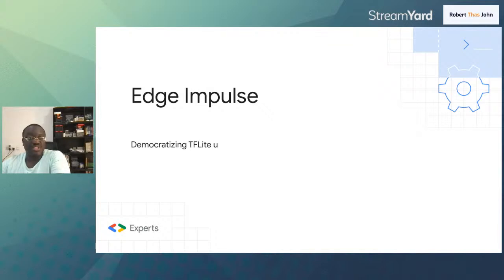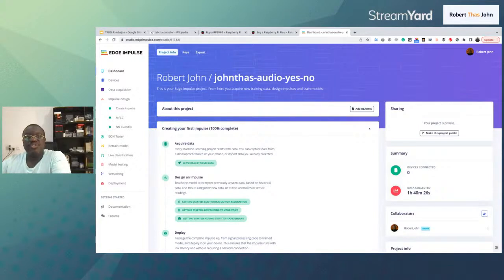Some of them even automate it. So things like AutoML on Google Cloud Platform show you how to train a model. Just bring your data, bring your labeling. It will find the optimal model for you using neural architecture search. So Edge Impulse makes that possible in a similar manner for embedded devices. And so I'm just going to walk through some screens that show an example of using Edge Impulse to train your machine learning model and deploy to microcontrollers.